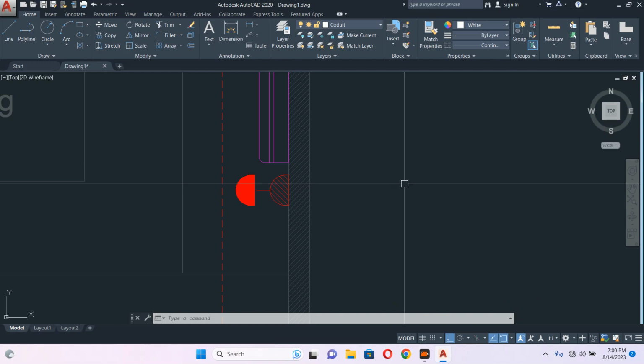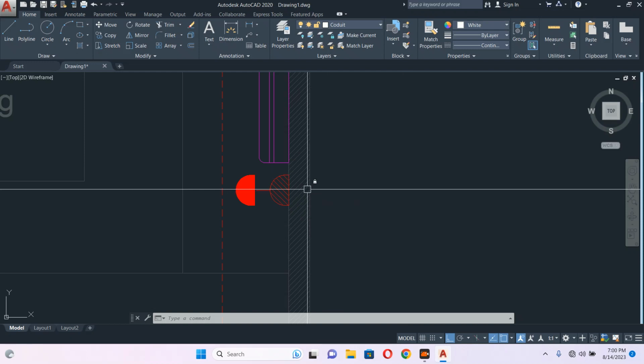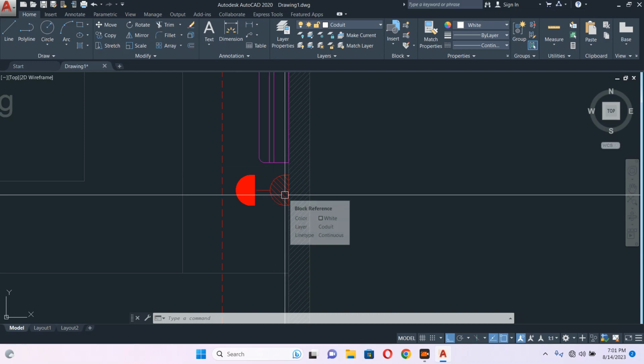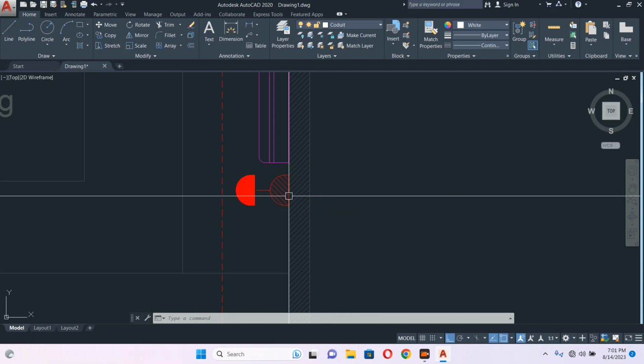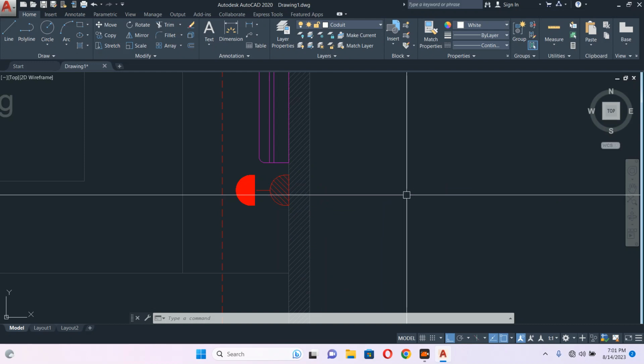Why? When high current comes, if the current is more than 20 ampere, the breaker will turn off. But if the breaker is 40 ampere and my outlet is 20 ampere, when the high current comes the breaker will never turn off, because it will wait until it reaches 40 ampere.